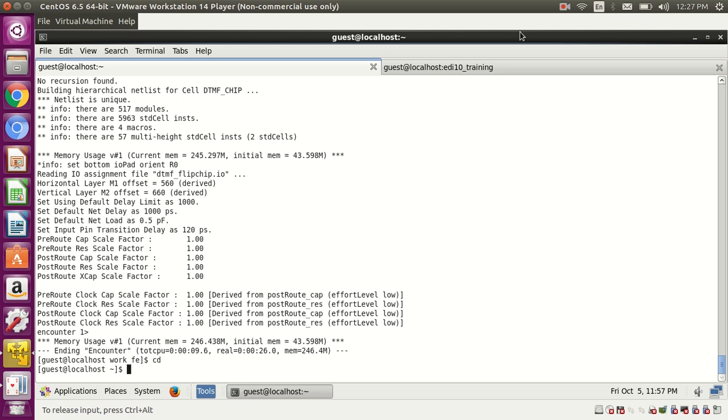So what we have done, we have added a flop, so the whole logic will change, because at one clock cycle this data is processing there, but the buffer register we have added now takes 2 clock cycles, so the logic needs to change and the frequency needs to change. That's how it will take a lot of iterations.